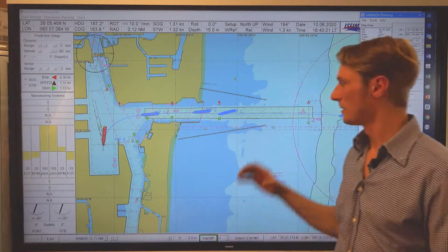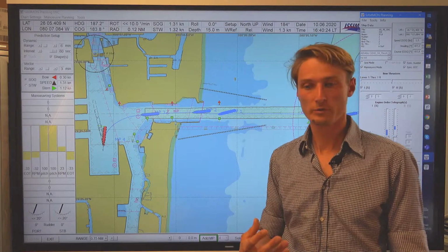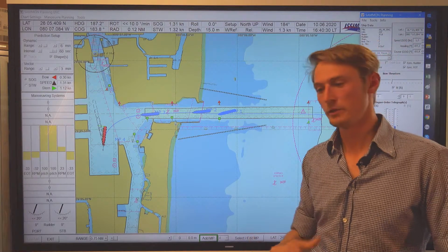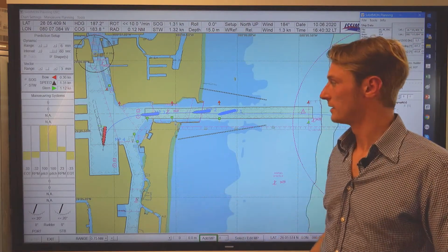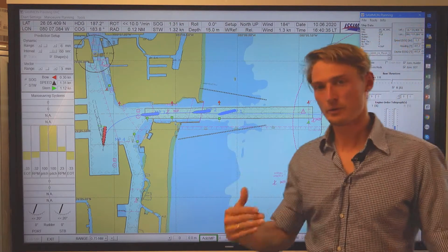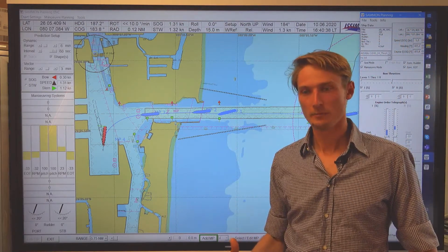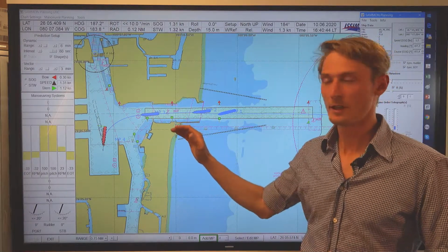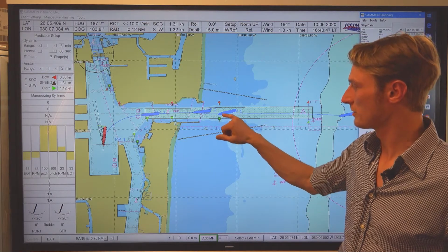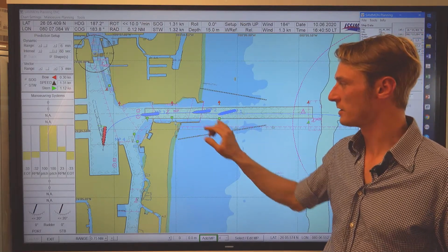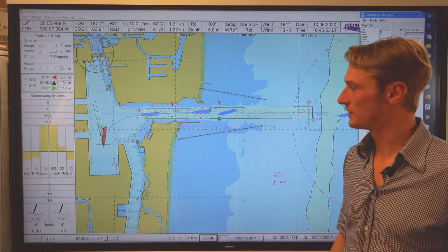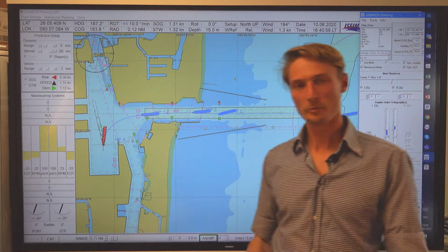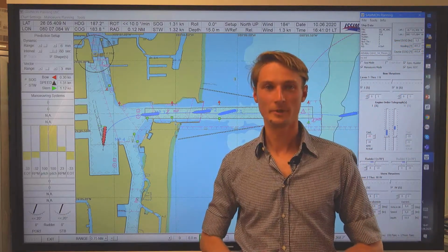When I plan a maneuver and I present it to my colleagues in the bridge arrival briefing, I present this strategy that I elaborated within a couple of minutes of trying. And this is what I'm going to try to carry out later. But reality is never exactly what I planned. So for me, it's good to know how many meters distance I expect to a breakwater, and what speed I expect passing the breakwater. And with this plan, I have a very good basis to come on the bridge, put the hands on, and carry out the maneuver.